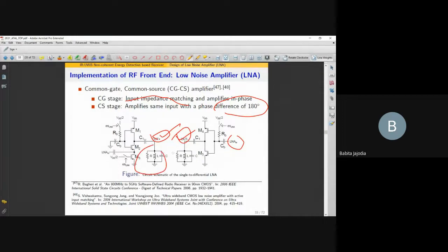And this RLC block will help us find out what bandwidth it needs to allow. And here you can see we have put the EN_LNA, so that we will enable the LNA only when we need it, right? We are not keeping it on throughout the operation. Whenever we require it, we will enable it and only then allow the voltage to work, and contribute to the power consumption.